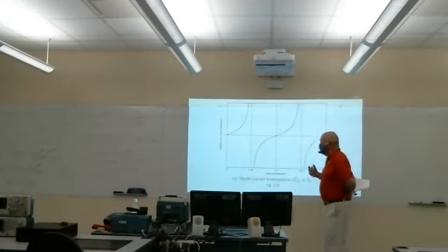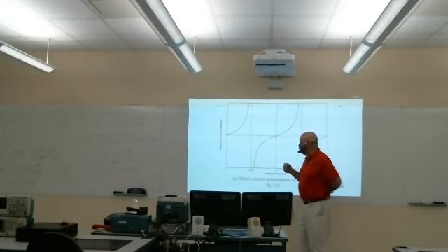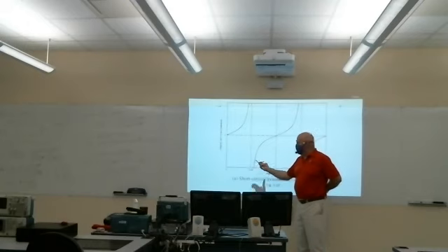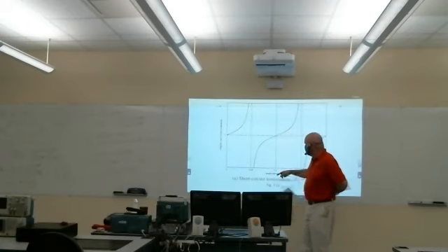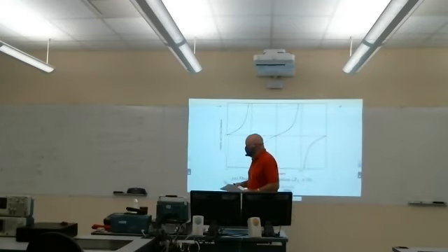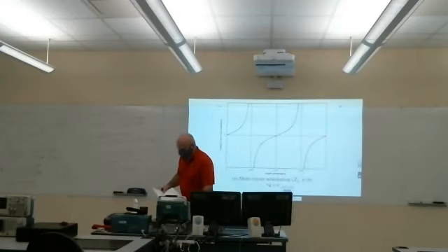So in most applications, when you're using this for impedance matching, you try to use as short a length of line as possible. So between 0 and lambda over 2, you can get any desired value of inductance or capacitance.